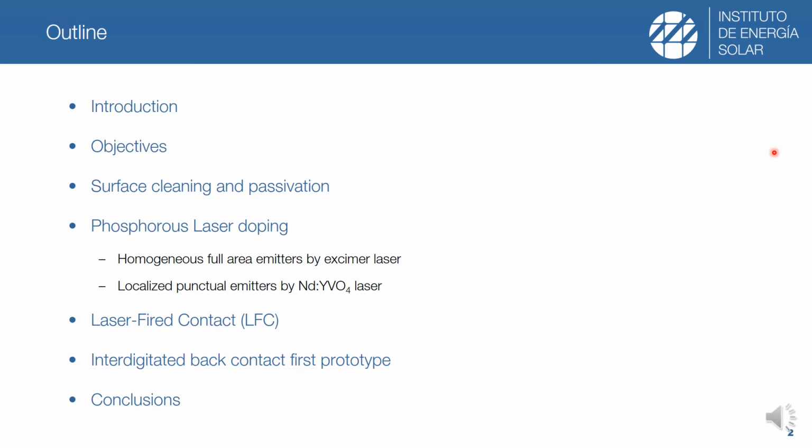So I will start this presentation by giving you a brief introduction to TPV technology, followed by the main objectives that have been addressed during this PhD. Then I will move to the experimental part, first talking about surface cleaning and passivation of germanium, followed by the phosphorus doping by means of laser diffusion processes, and localized ohmic contact formation by means of the laser fired contact